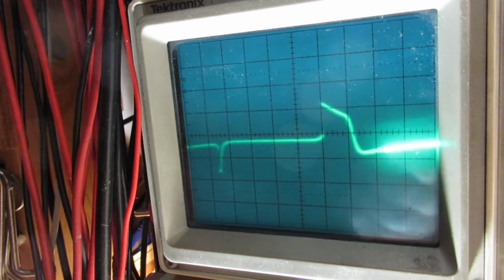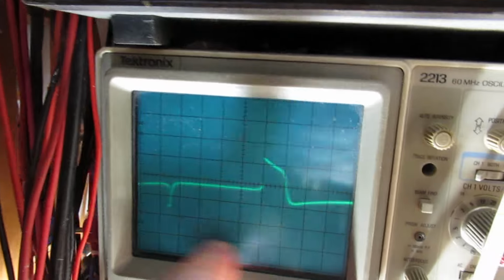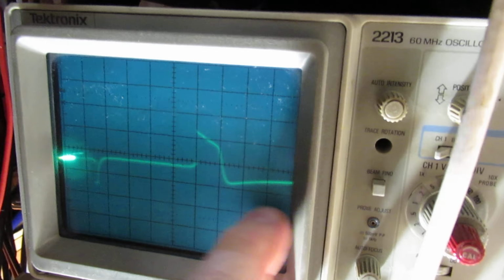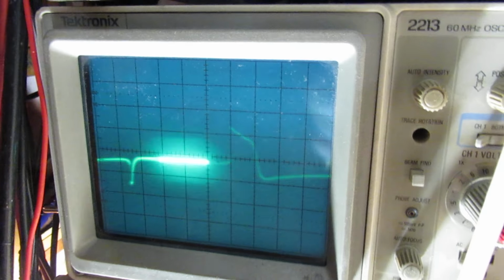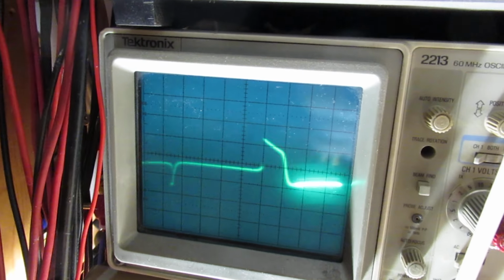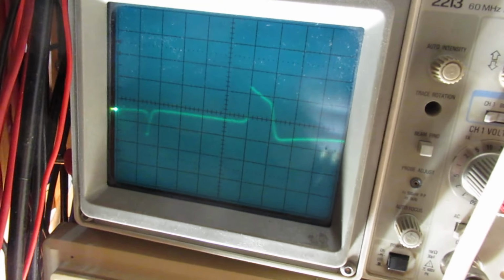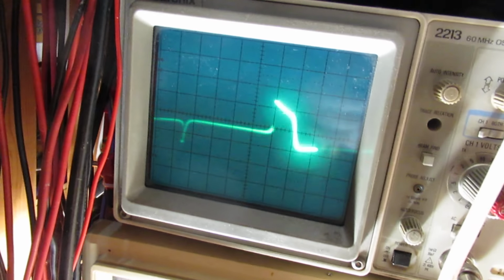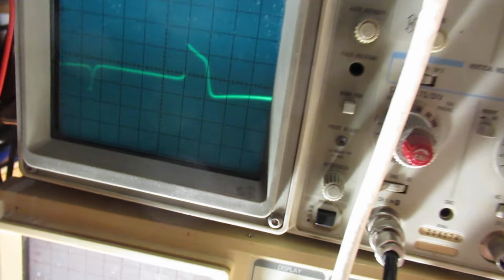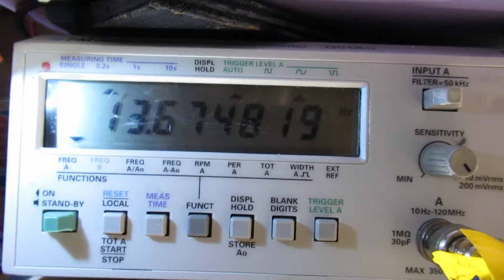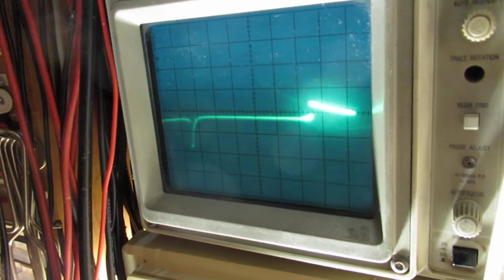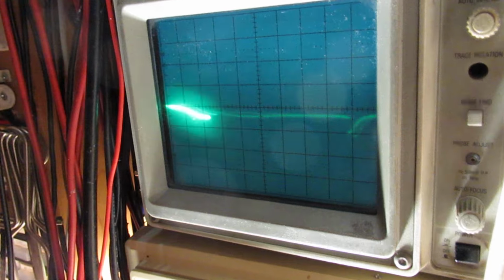When you are doing all these experiments, and I've done them through many years, you will always see these kinds of waveforms in the lower frequency band, I mean between 5 Hertz and 30 Hertz. Perhaps with a 555 that will work better, but anyway, we are on 12 Hertz, 13 Hertz. Turn the frequency potmeter again here. Let's see what happens. Well, the frequency changes somewhat.